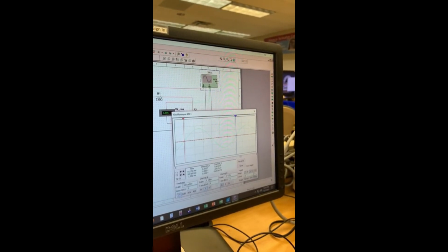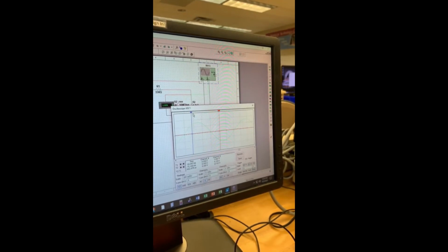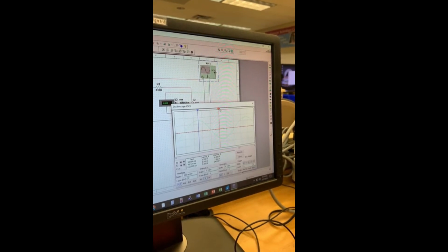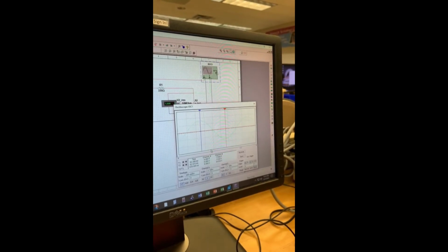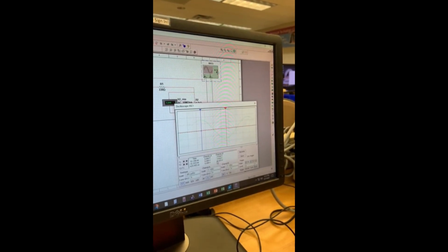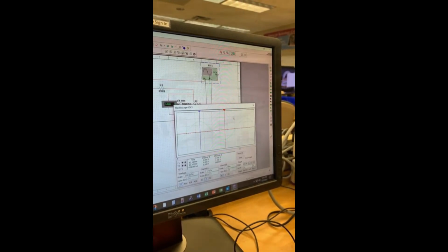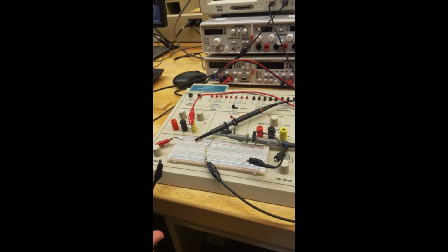Now I already set the whole thing up. It's going to be the same as channel 1. You hit the max for this, and then you hit the minimum for this. As you can see right here, 15.833 volts is the peak to peak in channel B, or channel 2. Now we'll show how one would set up an AC circuit.